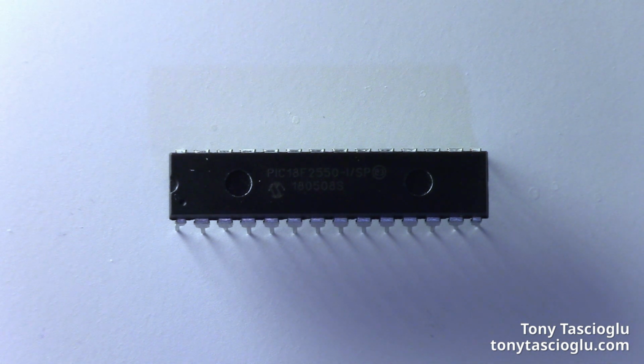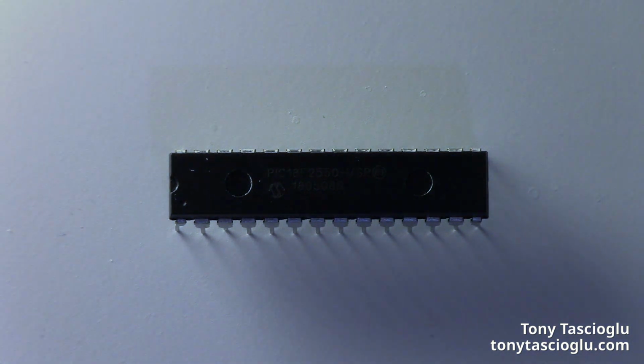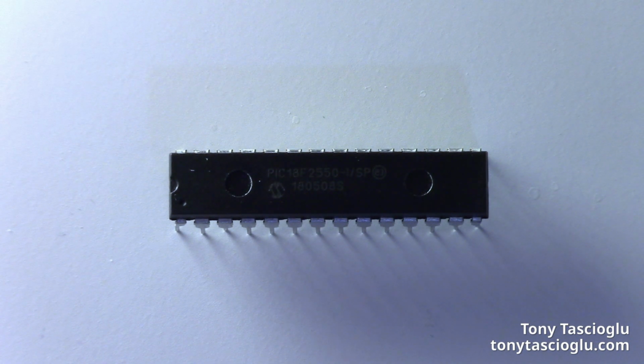The digital pins can be used as digital inputs or outputs. There's also a built-in 10-channel analog to digital converter with a 10-bit resolution, which is the same resolution as Arduino chips. The pins can also be used for two onboard built-in comparators. There's also plenty of connectivity, including the standard UART, SPI, and I2C buses. There is one built-in 8-bit timer and 3 16-bit timers.